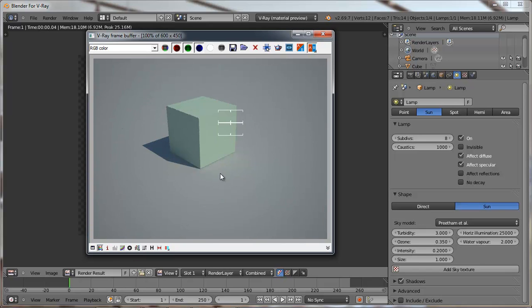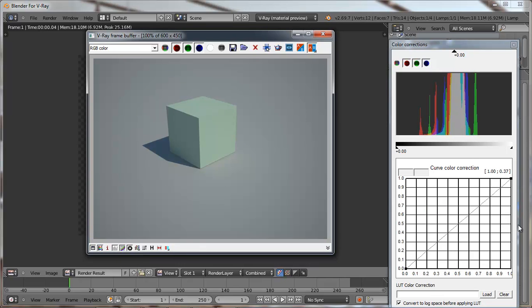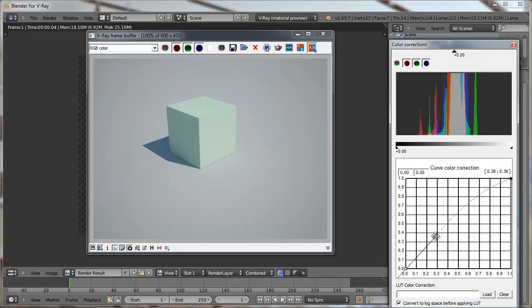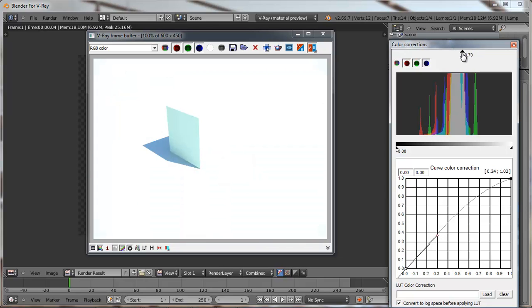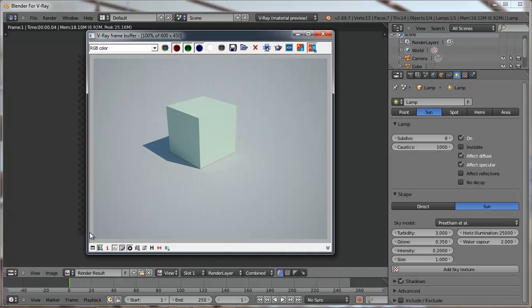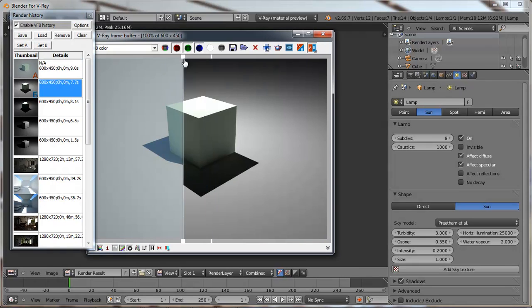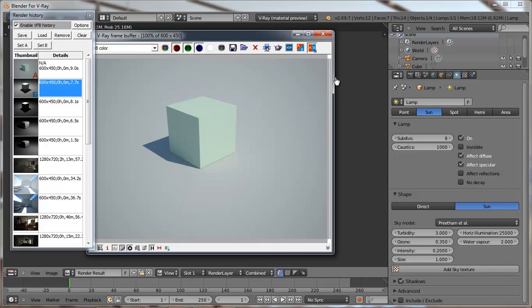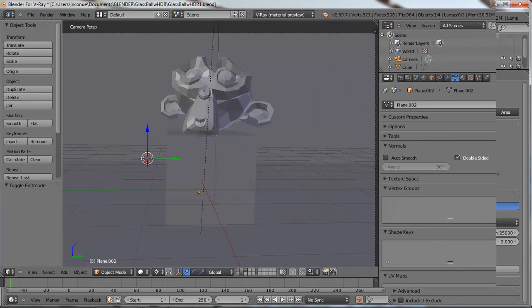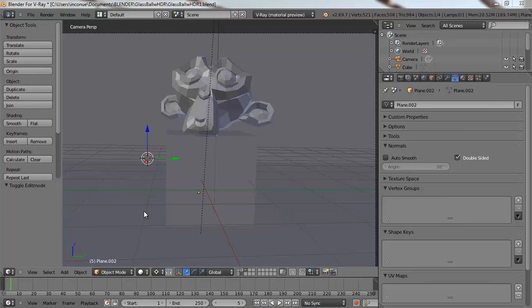In general, we have global illumination. You can activate it here. We can change the value of intensity, luminosity. You can play with that. Okay. Now we make a comparison. Save. Set B. And now we can see we have more light coming into the scene. The first part we talked about lighting in general and some settings under the tab.